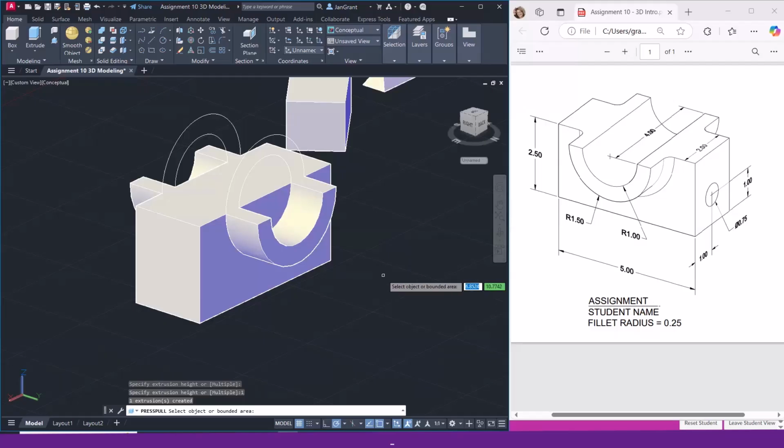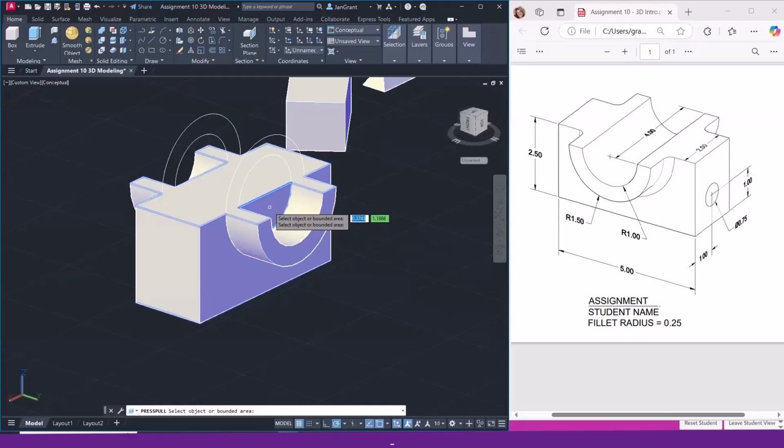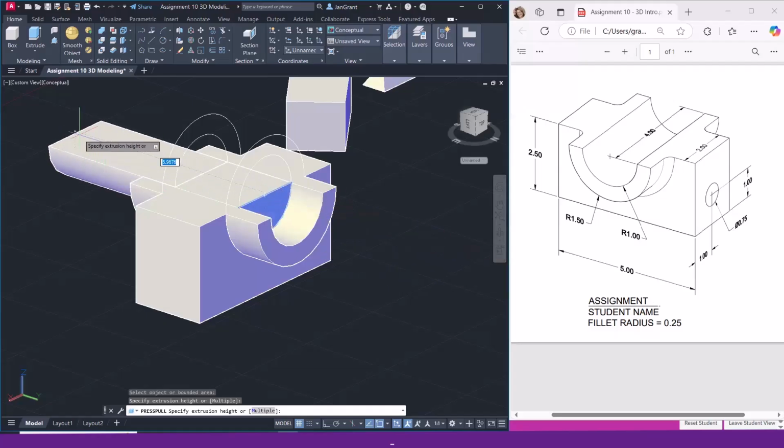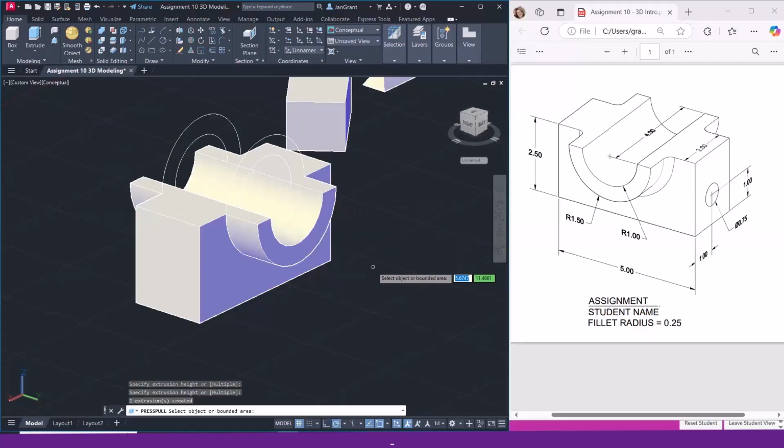Now, because we still have to get this centerpiece out, we're going to use press pull. We're already in press pull, so it's up to you if you went out of it and back into it. Sometimes you can't see what you're clicking on, but you have to just do it, like it doesn't highlight correctly. Like in this case, it's highlighting the top surface. But I know that if I click this inside kind of half circle right there, you see how it grabbed it? So instead of pulling it out, I'm going to pull it back to kind of cut it out. So I'm going to go here and click. Now I was able to use press pull to get that out. Now guys, I'm clicking inside the space, not on the edges. Remember that.